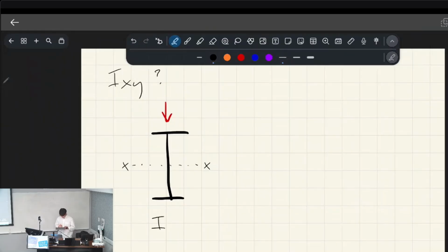So that's where we get, when we do our calculations for moment of inertia, we just call that x. And that's because our product of inertia, when you work out the calculations and do all the balancing from last time, so if you remember the quadrants, this section is positive, this is positive, this is negative. So it all balances out, and it works out to be 0.